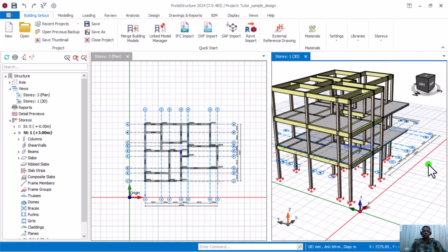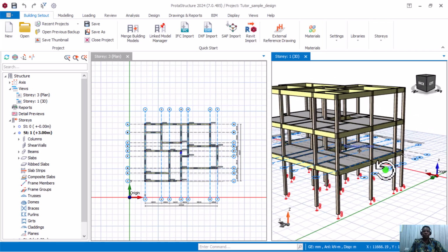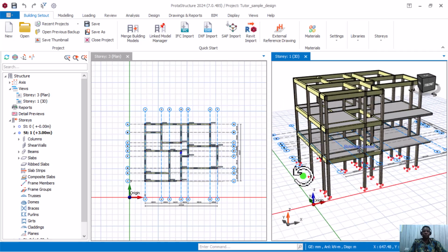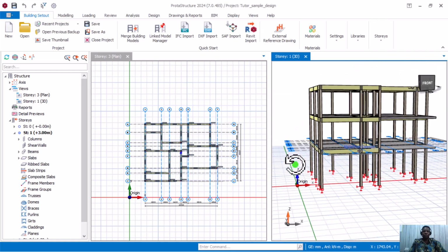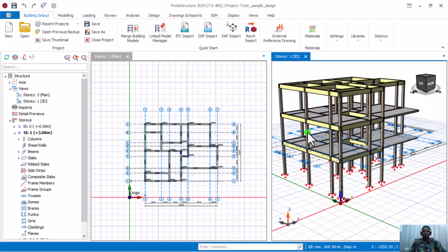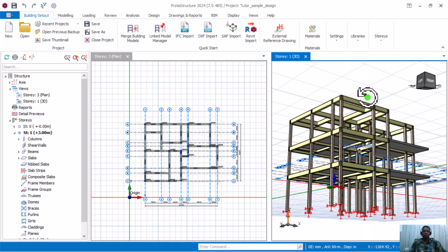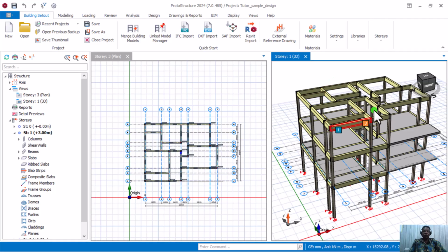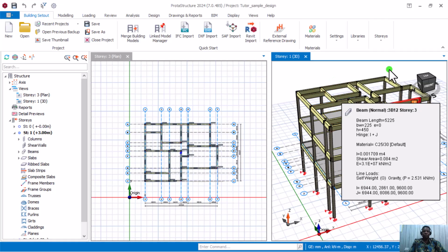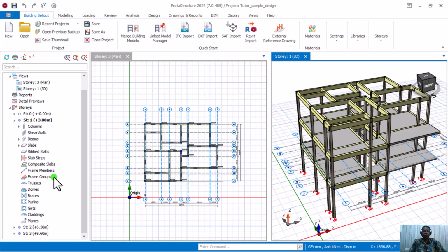Because I untick the slab, you can see in the first situation, I generated everything down here. And in the second one, I have to untick the slab because I don't want to generate the slab. In this situation, I'm having a hip roof. So I'm imagining that I'm going to be having a roof here, not a slab. Okay, so it's not a slab roof. It's a kind of a hip roof where I'm going to introduce a beam that is going to carry the roof. So that's why I have to take this beam. But in this situation, right here, we are at the third floor, right?